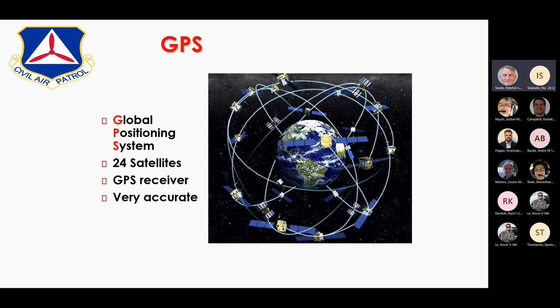And also, when you're reporting your GPS positions, make sure that you're identifying what you're using by saying this many degrees, this many minutes, decimal minutes, and that way someone won't accidentally write down degrees, minutes, or seconds. If you do accidentally give it to them in degrees, minutes, and seconds, you should say so many degrees, so many minutes, and so many seconds, and at least they'll understand what you've given them.